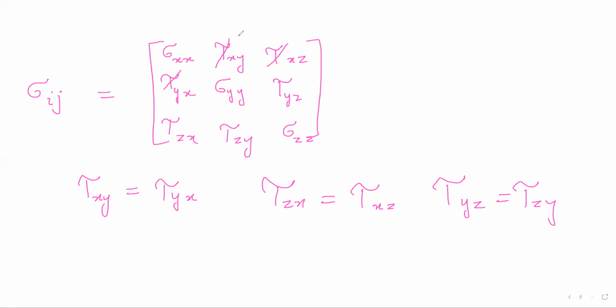What matters is that it is acting on the x face in that direction. So this is the x face and I'm pulling it. That's a normal stress, right? This is my x plane, this is my y plane, and I'm pulling it from here. That's a normal stress. But if I put my hand over it like this, that's a shear stress, because the normal is x, this being an x face, but the loading I am putting on it is in the y direction. So that's a shearing. The fact that it's acting on an x plane in the y direction makes it shear. The fact that I'm pulling it, on the x face acting in the x direction, makes it normal. In textbooks, that's why many times they use sigma and tau differently. But even if someone uses sigma everywhere, with the distinction of xx, xy, xz, you should know that xx, yy, or zz means normal stresses, and xy, xz, yx mean shear stresses.